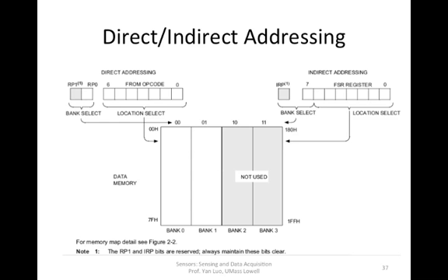And by looking at the location value from the instruction itself, we know which location in the bank. So, 2 steps. First, find out which one of these banks. In our case, 4 banks. If we have 0, 0 here, we know that's bank 0. If we have 74 here, that means 74. So we can locate that value, and then we're done. The microprocessor is able to grab the value to perform whatever operation.